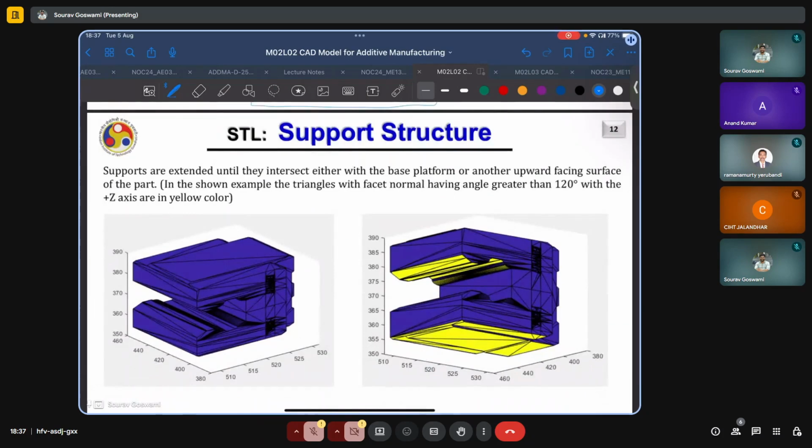And we can also make intelligent guesses, such as the bottom surface here, highlighted in yellow, will require supports because that entire projected area is unsupported, but also the bottom surface of the build itself. And the reason for that is actually pretty simple.